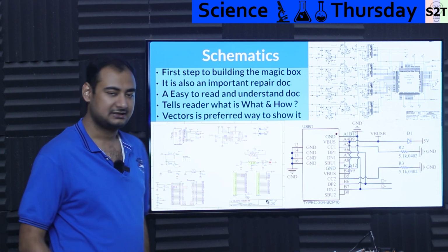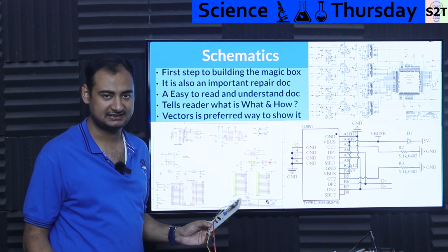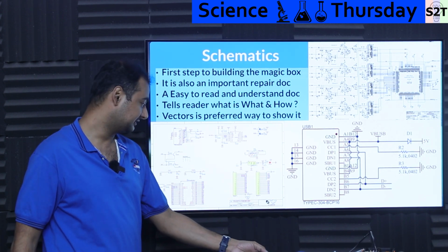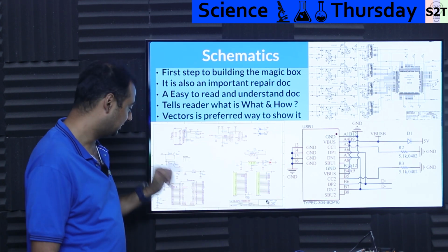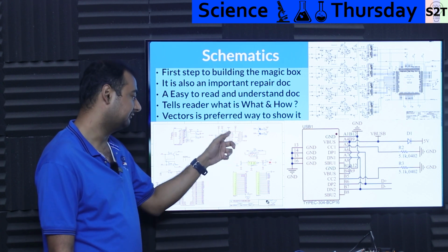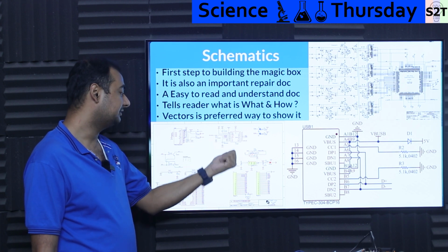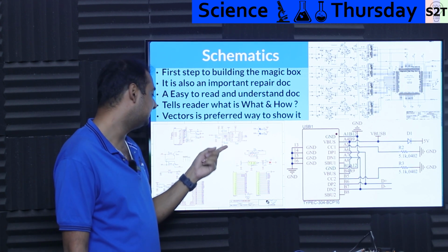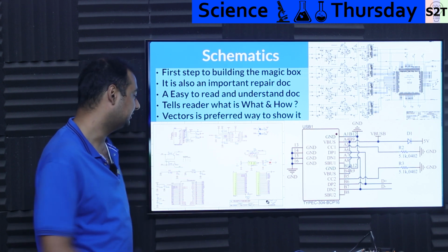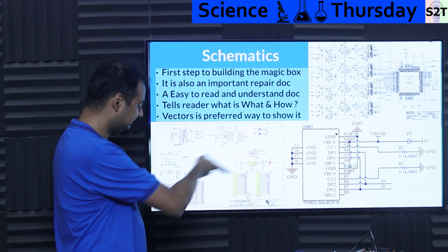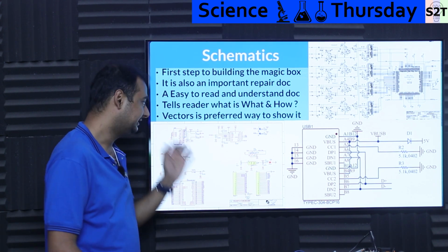For example, it's like, okay, this IC is communicating with PC. How the heck is that happening? I look at the schematics. First thing I'll find, okay, there are pins. Okay, good, awesome. Pins are talking to what? Pins are talking to the module. Okay, awesome. How the heck is the module talking to something else? Okay, I will look into this and I'm like, okay, this is the chip CH343P. And this puppy is communicating with D plus and D minus. D plus and D minus is going to this D plus and D minus. This is USB-C jack. That's how I can follow it. This is USB. This is the converter. This is the module. Modules have the outputs. That's the whole point. What is happening, how it's happening. This is what it means.